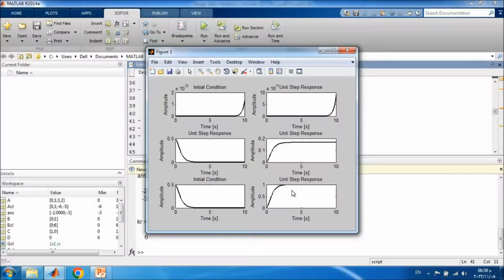But the problem is, if you have a very fast system, you need to enlarge the control law in order to obtain the response you want. So in pole placement, you can change the poles of the system, but you can't control the control action. And that's what we will see in the LQR, the Linear Quadratic Regulator, where you have the ability to choose between the response of the system and the control law.